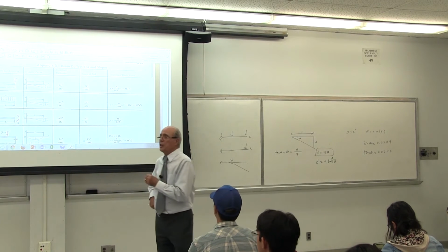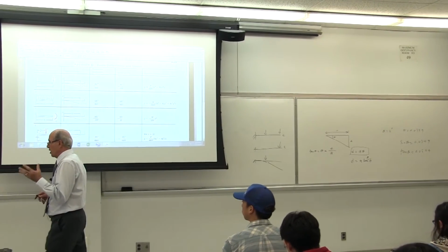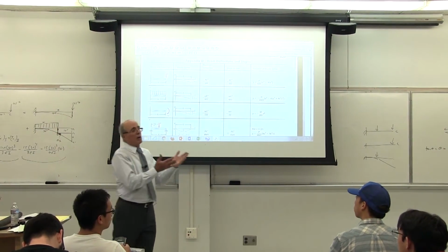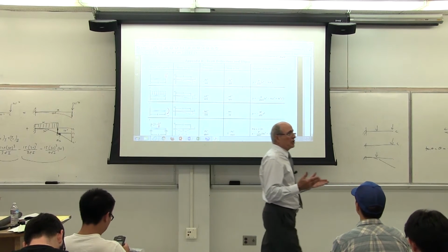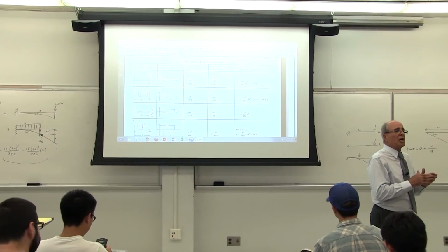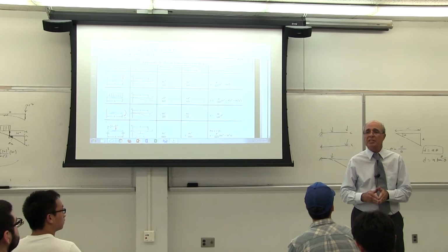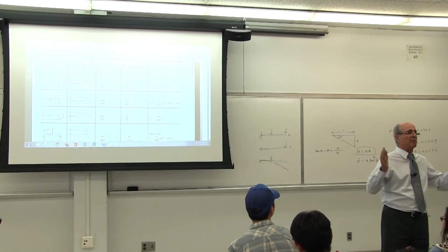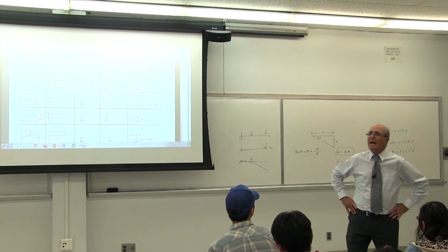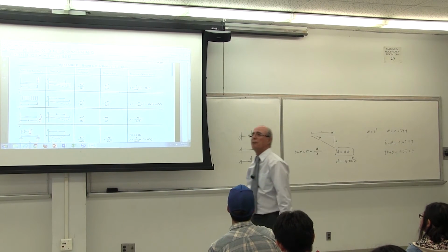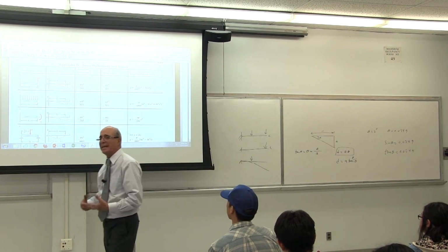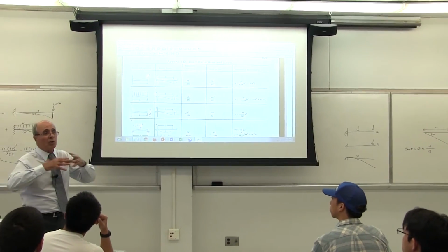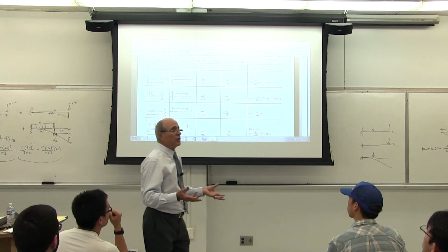Actually, if the deformation is not small, I cannot repeat this for this class and then move on with the lecture. It is such an important thing to know. Actually, everything that you learn in ME 218 works if the deformations are small. If the deformation is big, none of this will work. So you cannot apply that to a plastic deformation. It has to be an elastic material. We are talking about still small deformation and all this slope.